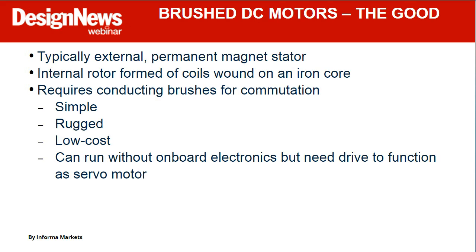So let's dive right into the motors. Brushed and brushless DC motors. Now, there are not a million, but a whole slew of different implementations of motors, but in general, for a brush motor, you can be thinking of it in terms of a permanent magnet stator on the outside, then you're going to have an internal rotor with coils wound around and a toothed iron core.